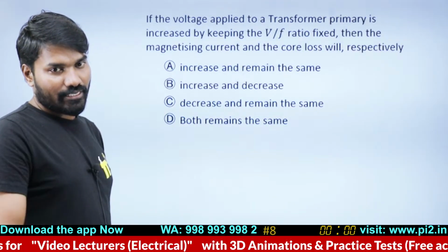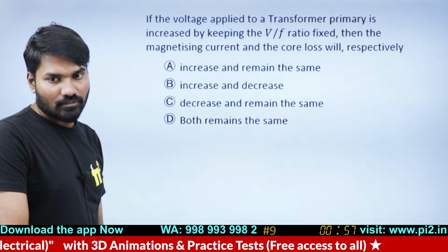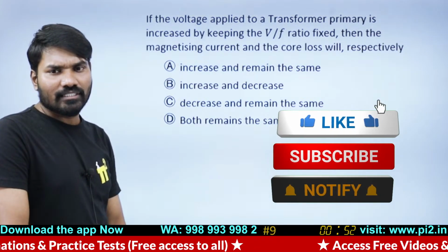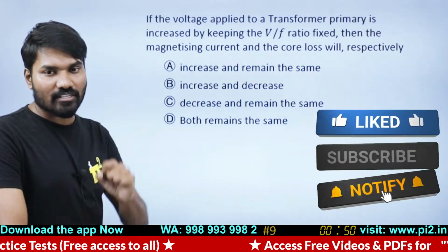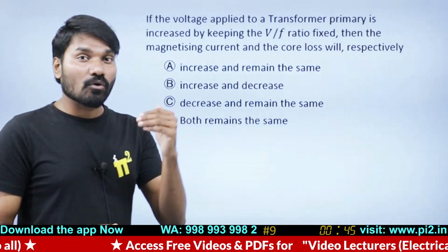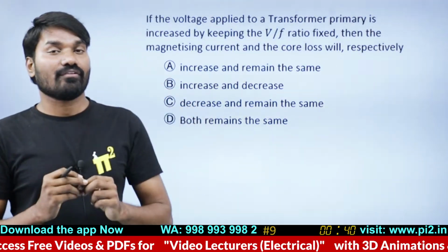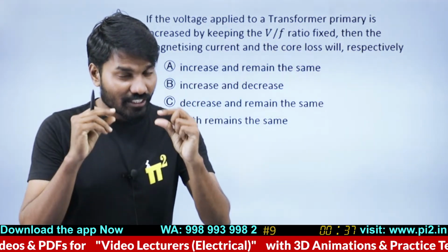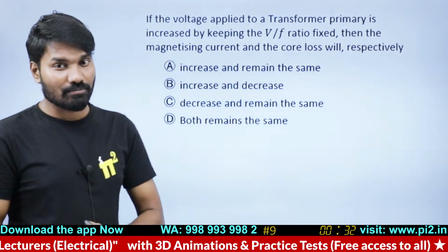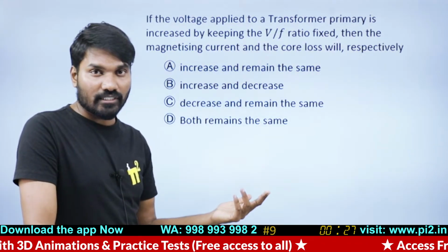Okay. Next question on the screen. Yes, guys, parallel operation is possible. It's not about a possibility, Sweetie. Parallel operation is possible for any per unit impedance. For a proper load sharing, it should have the same per unit impedance, but with respect to a common base. That's what I'm trying to explain. The point what Sweetie is asking is a valid point, which I explained already.